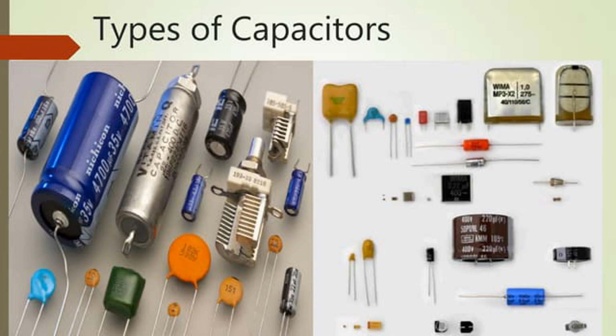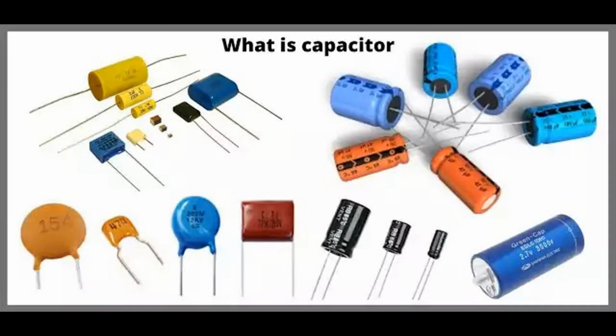The voltage rating is typically specified in volts, V, or sometimes in direct current, DC voltage, for example 16 VDC. The voltage ratings can vary widely, ranging from a few volts to several hundreds of volts, depending on the specific capacitor type and size. It's important to note that operating a capacitor near or at its maximum rated voltage for prolonged periods can reduce its lifespan and reliability. To ensure long-term performance, it is generally recommended to operate capacitors well below their maximum rated voltage, allowing for voltage spikes or variations in the circuit.